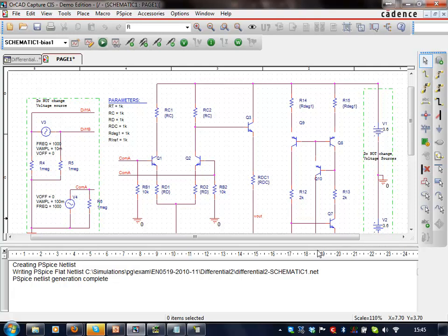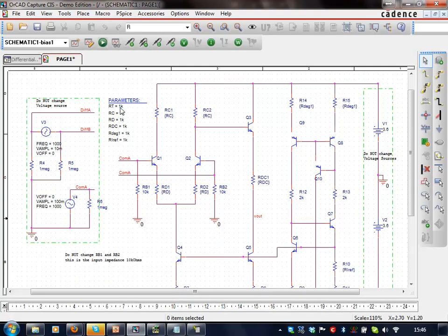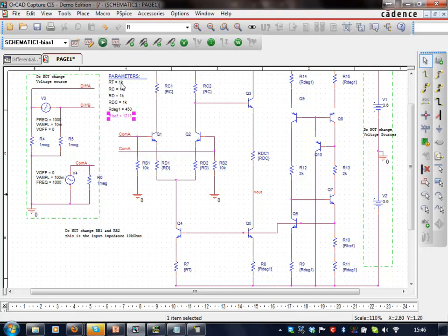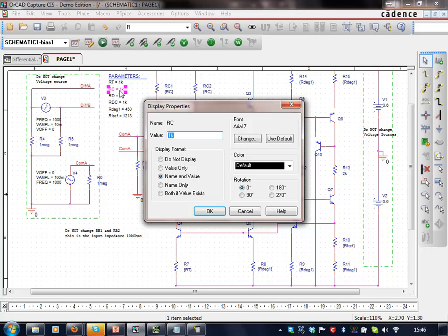Here we have OrCAD running, and we have that design inside. So let's put all of our parameters in place. Let's start off with our degeneration resistor. That was 450 ohms. Our reference resistor was 1213 ohms. So that's this one and our reference line, and our two at the top. The degeneration in the output stage was using the same current, so that's the same value. Let's put in RT. RT was slightly different, and that was calculated at 95.43 ohms. Our collector load resistance was 2600 ohms. Our degeneration resistance was 40 ohms. And our output stage resistance was 786.